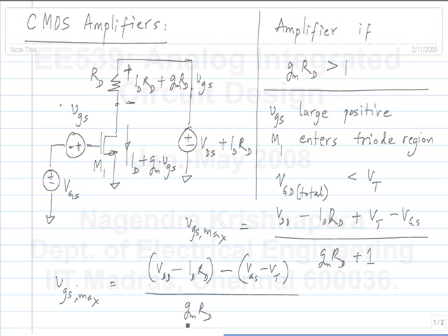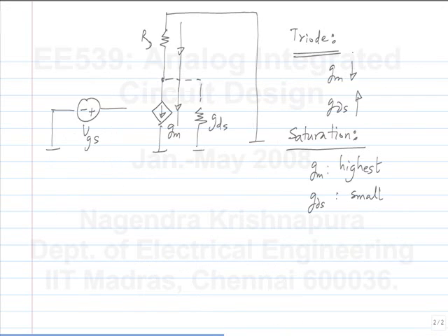That is the output divided by gmRD will be the input increment. Okay. Why do we get gmRD plus 1? So, the input itself is increasing, right. The input goes up and the output goes down. So, the point at which it enters triode region is different when the input is increased than when the input is 0. Okay. So, that is why we get gmRD plus 1, but you can see that for very large values of gmRD, you can neglect the 1. So, that means that the input signal is really small. So, this is the largest increment we can have, and within this increment, we sort of assume that it works as an amplifier, right. On the negative side, is there a limit?